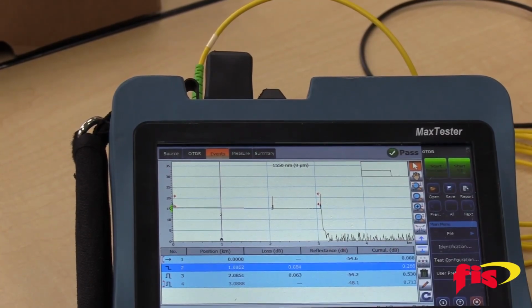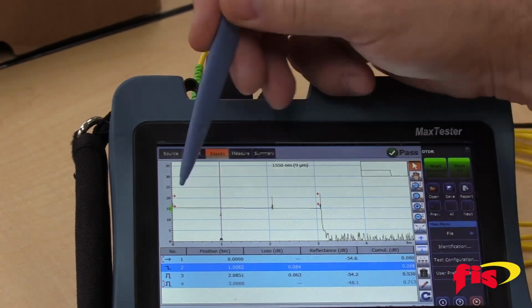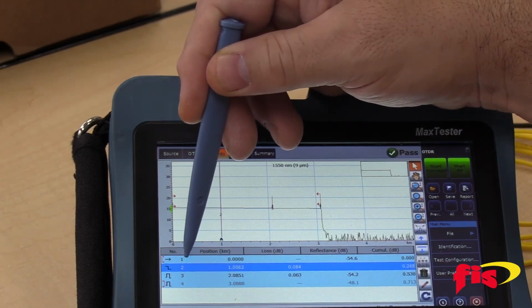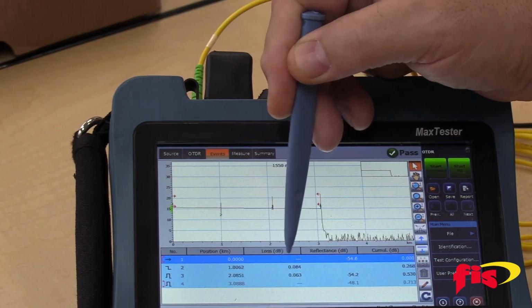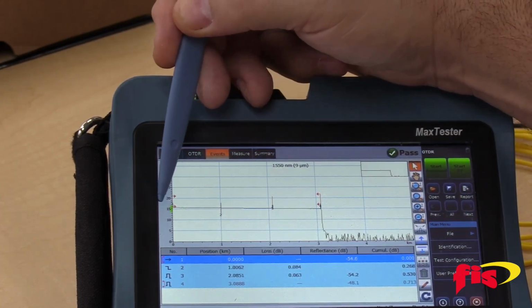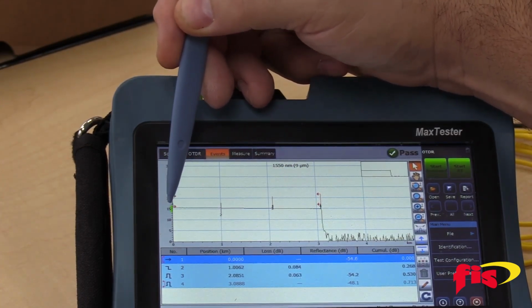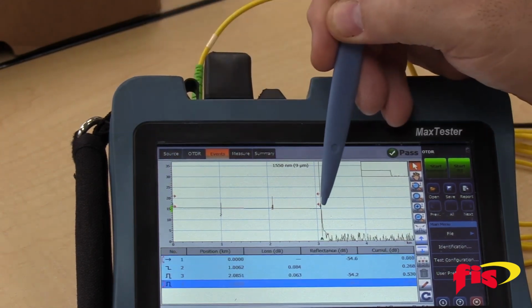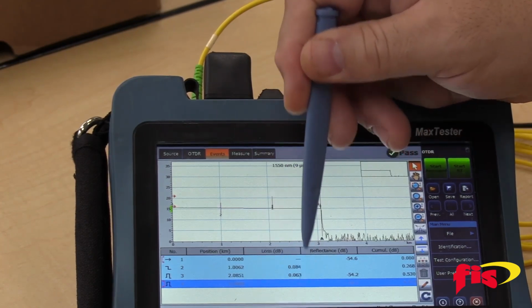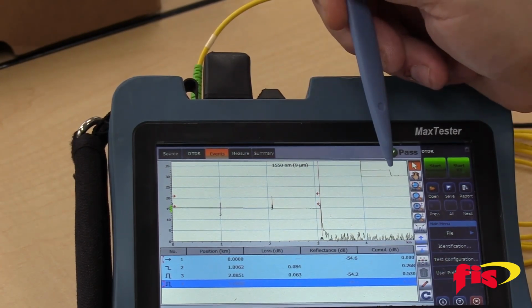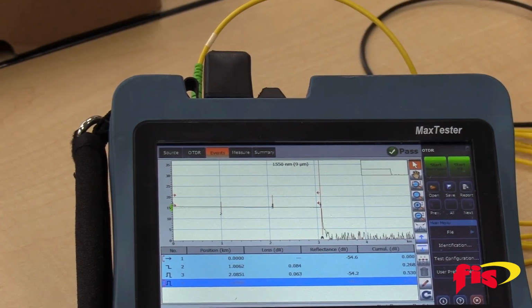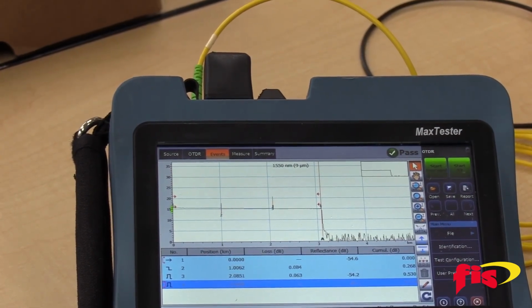Now what you'll notice is, see my zero position? I don't have information there, no attenuation, because I can't wrap this event. I can't get my prior power value to get attenuation. You'll notice on the end, same thing, my attenuation values are non-existent for the end connection. So we're eliminating that in the test, and these are two of the most important things we need to test.